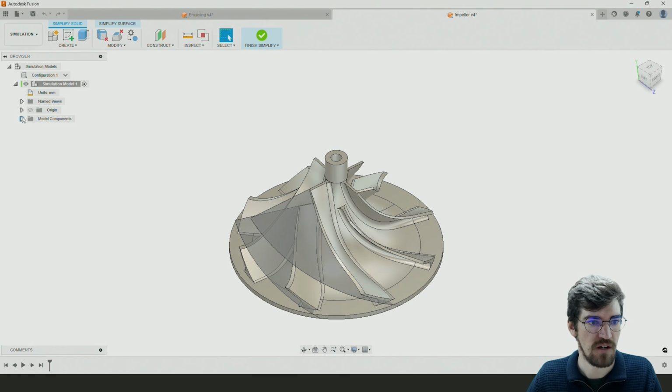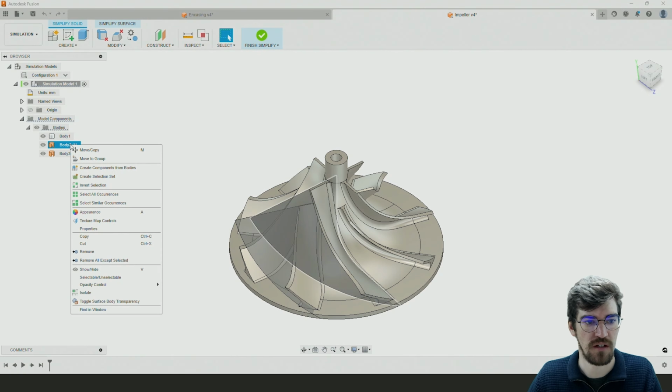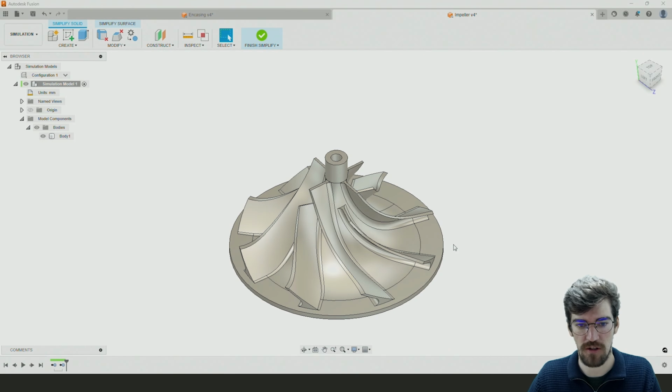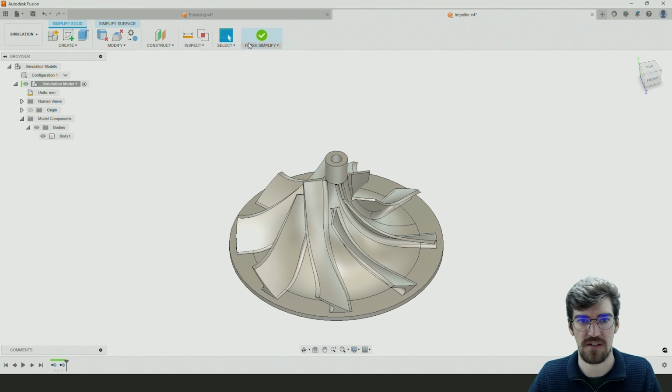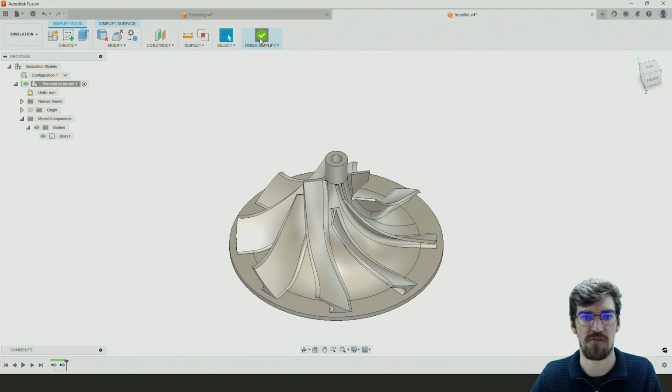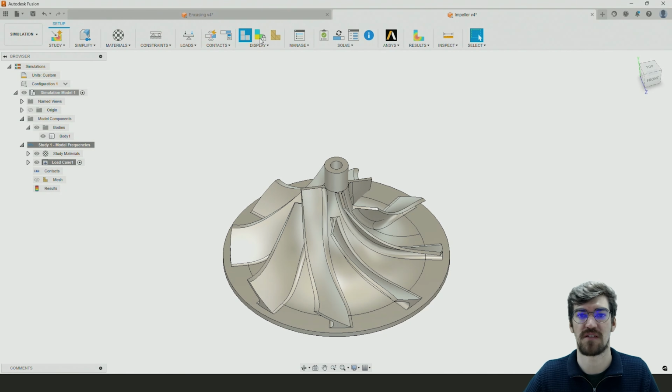So in this case, what we're going to do is look at the model components, and we've got the two surfaces over here. I'm going to right click and remove them over here. So we've no longer got those surfaces, and it's not going to take that into consideration. Generally speaking, the simulations don't like working with surfaces unless they are already meshed and are considered part of the study. In this case, it would be giving us some conflicting results along the way.